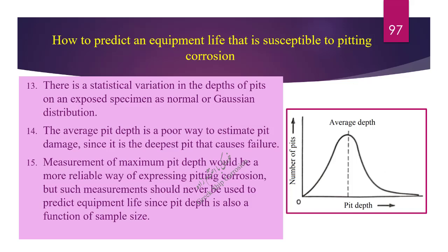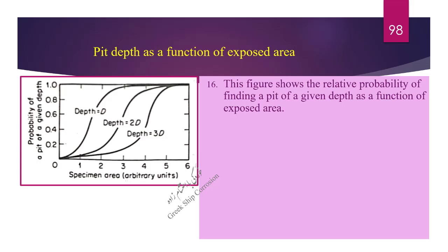Measurement of maximum pit depth would be a more reliable way of expressing pitting corrosion, but such measurements should never be used to predict equipment life since pit depth is also a function of sample size. Pit depth as a function of exposed area.